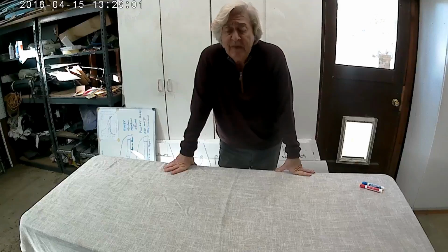And recent ground tests show that the flow is in pretty good shape, but it could be better. Still getting a little bit of span-wise flow. So I did a series of tests with just full-scale mock-ups of the wingtip panel, and I have those behind me here, and I'm going to talk about them in a minute. I'm testing different elevon shapes and looking at the flow conditions and what minimizes the span-wise flow. I'm using some of the experience that I have, gathering information from others and blending it together, and discovered something very interesting along the way.